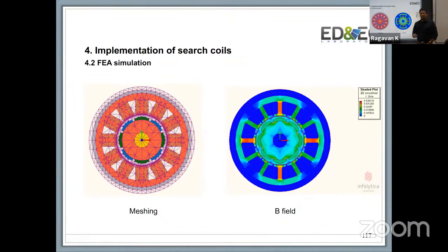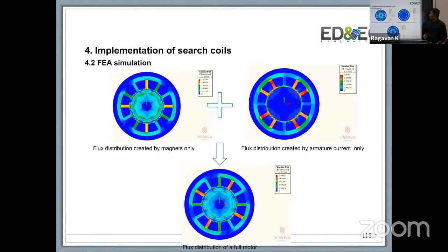You can mesh it, you can plot it, and it gives you a 4-pole design. And that essentially gives you the field reconstruction concept once again. Except what we're doing here is not field reconstruction with the phase winding. Instead, we are trying to use a surge coil to break down that same exact component of field that we talked about at the beginning of the session yesterday. When we talked about microscopic energy conversion, we said that if the field rotates, you can measure the voltage across the phase coil. Well, if we have another winding sitting in the motor that is unenergized, you can still measure the same voltage.